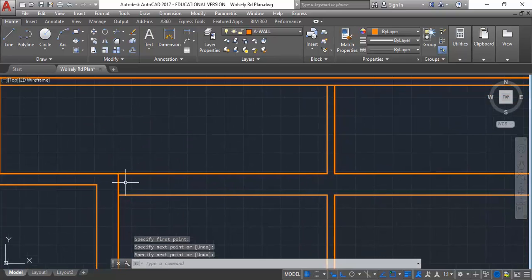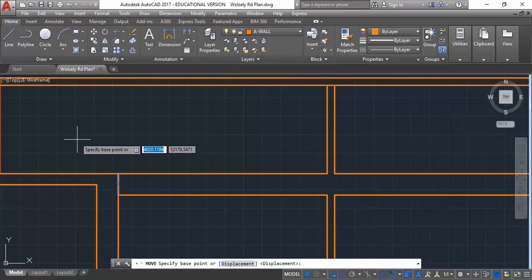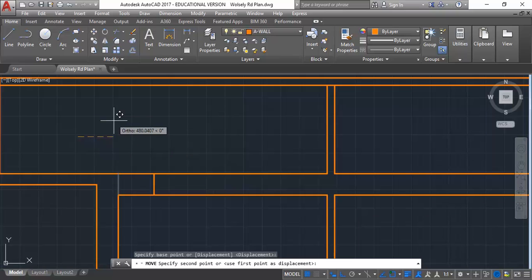Can't emphasise that enough. Most of the problems people have drawing doors and windows are because they go too far drawing in the framing before they even know the opening size. So you've got to set the opening out first, always. And so here I've drawn my line. I'm going to move that across to the right, this time just 100 mil.